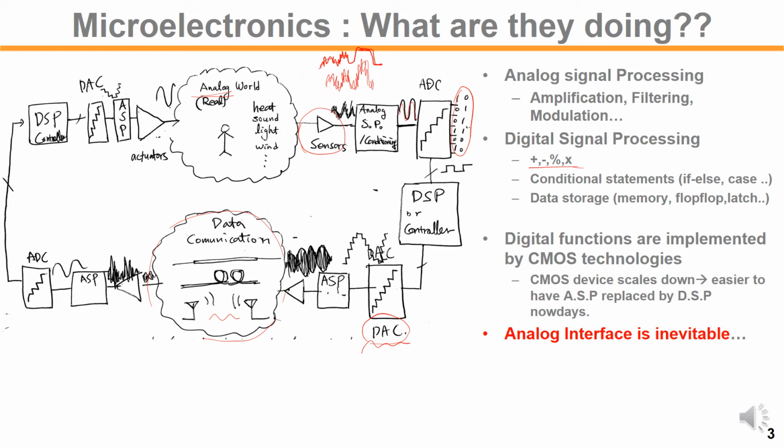After the digital to analog converter, the output waveform is a stepwise, quantized signal, because the number of levels of analog signal we can generate out of a DAC is limited. For example, if the DAC has a 10-bit input, the number of output levels is 2 to the power of 10, approximately 1024 levels.